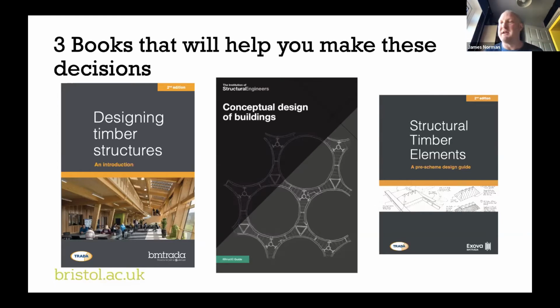That's when we should be thinking about this stuff, literally right at the beginning. By the time you've got the grids and the column layout and the loading sorted, by then it's too late. You've already excluded or included timber as a design solution. So if you want to be designing with timber, you need to start with that, and that book will hopefully enable you to do that.